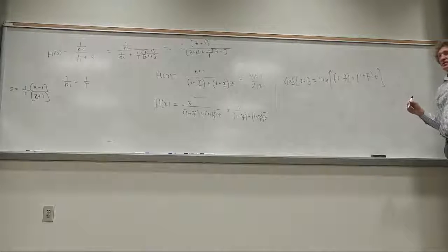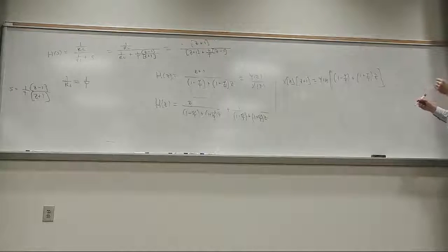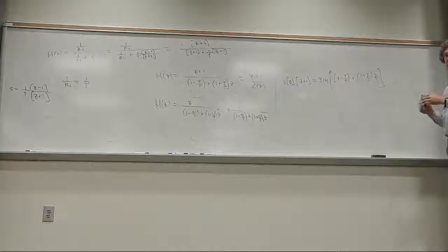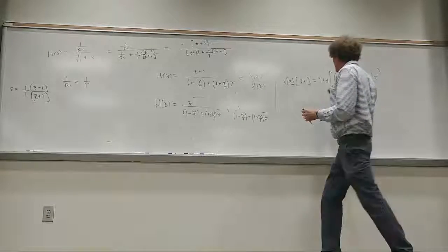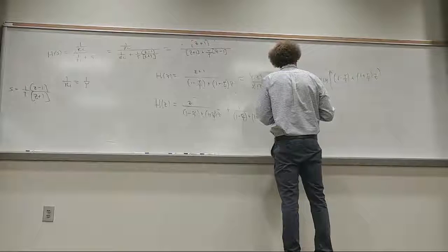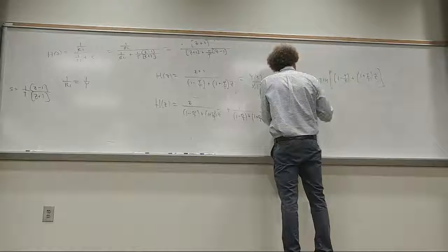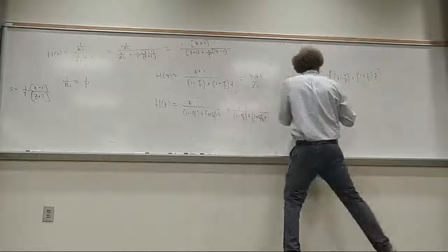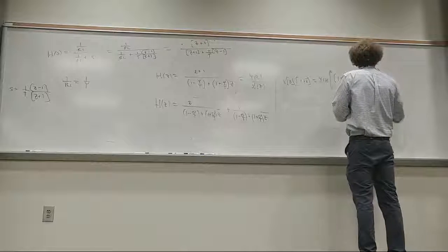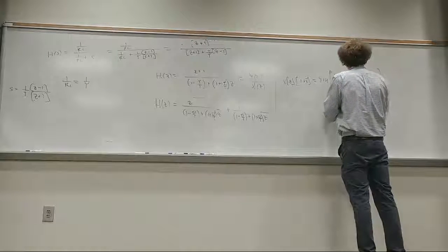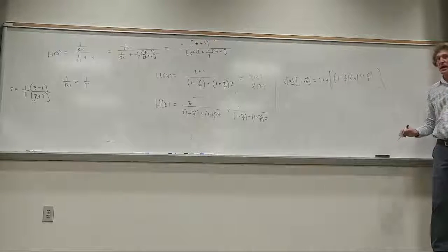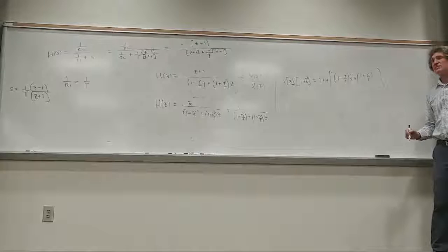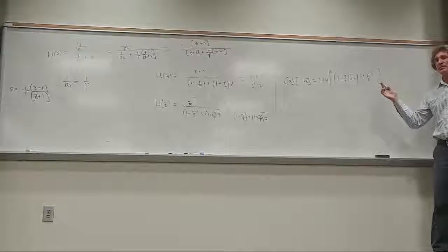Now, we're going to turn it into a difference equation, all right? Here's what you can do. Because of the z, we can divide both sides by z. With me? If we divide both sides by z, that becomes 1, this becomes z to the minus 1, this becomes 1, and this becomes z to the minus 1. Are you with me? Now we're going to create the difference equation.